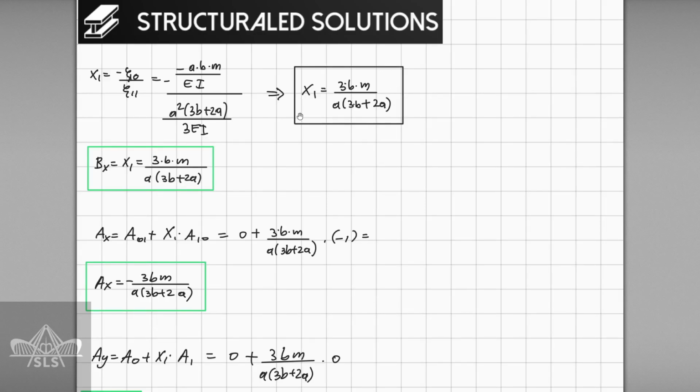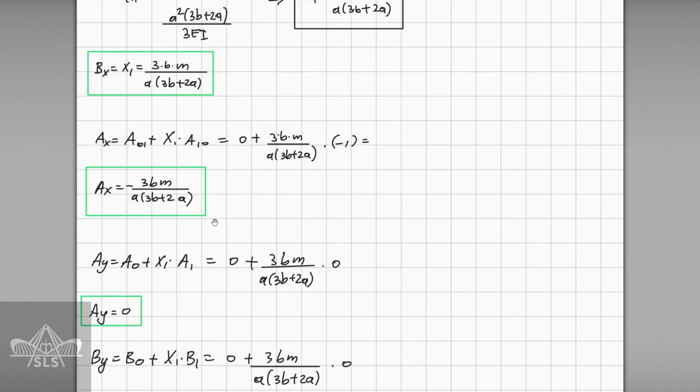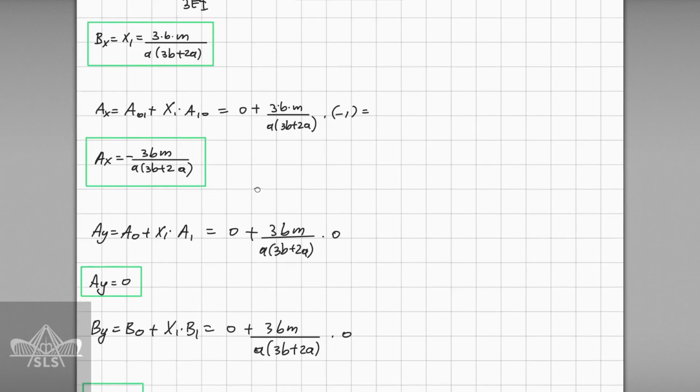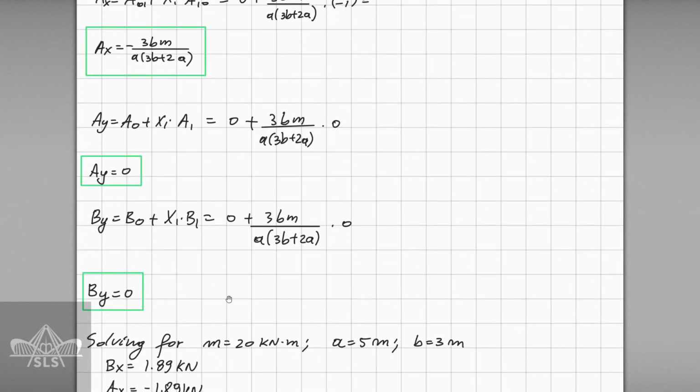So this is a good way of solving the exercise, and we can utilize this result if in the future those dimensions or those bending moments at the corner joints are going to be changed. Next, by utilizing the force method again, it's now easy to determine the other support reactions for our structure as shown here, and we get this following value for the AX support. We get AY 0 and BY is going to be 0.